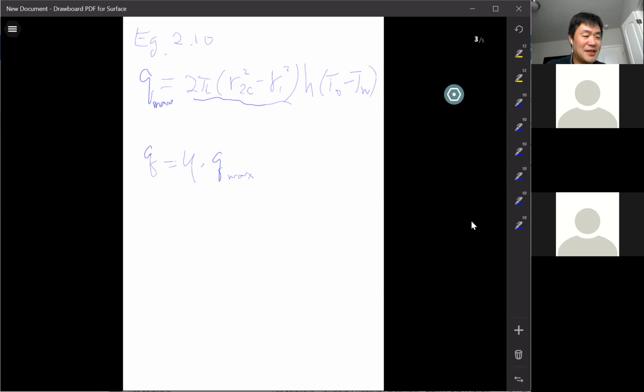We're trying to calculate the surface area on the top of the fin and the surface area on the bottom of the fin. We're adding them together. They are the same. That's why there's a 2 here, right? Is that right? It's so quiet. Yeah, it makes sense. Okay, so we calculate the one surface area first, then multiply by 2, to combine the surface areas.